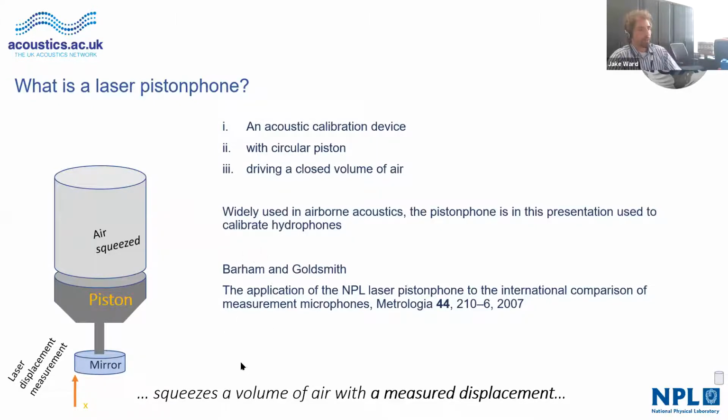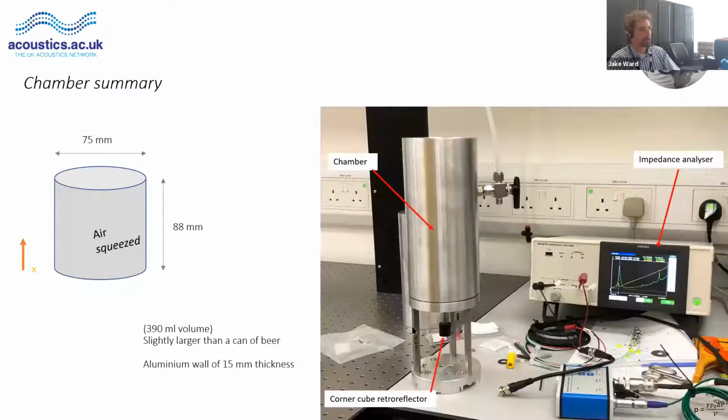Richard Byram is a collaborator on this project, and used to work at NPL and published this work on laser piston phones for microphone calibration. So we're going to squeeze the air in an aluminium chamber and measure the amount of squeezing by displacement. And we have an actuator there. There's an impedance analyzer for the actuator we're using. It's multi-layer piezo ceramic, and the volume of the chamber is just 390 milliliters, so a can of beer, if you like, of air with a hydrophone in it.